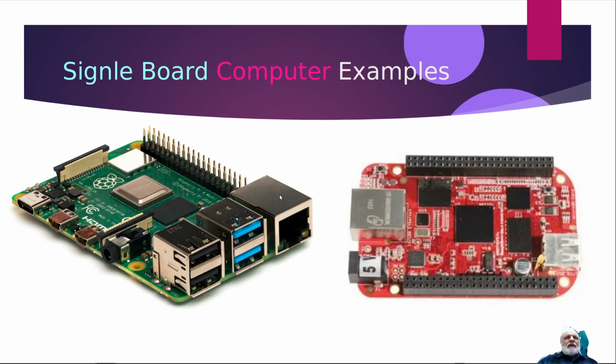All right, so here on the left we have a Raspberry Pi. This is a Raspberry Pi 4. That's a really cool device. This one had built-in Wi-Fi. The Raspberry Pi 3 didn't have built-in Wi-Fi. This also can support two HDMI, so you can run two TVs or monitors using micro HDMI connectors. These are micro HDMI connectors on here. And then it has these 40 pins over here. These are your I/O. And then on the right I have a BeagleBone Black.